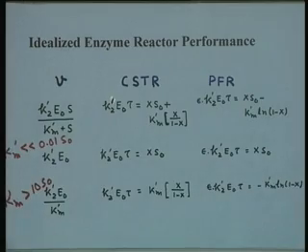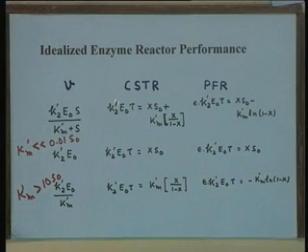But in general, with the increase in fractional conversion, the productivity will go down in both the cases, because you will see from the reactor performance equation that the decrease in tau will be much faster compared to the increase in fractional conversion. So in general there will be a decline in productivity as the fractional conversion increases, but the relative decrease will be more pronounced in the case of CSTR than in PFR.